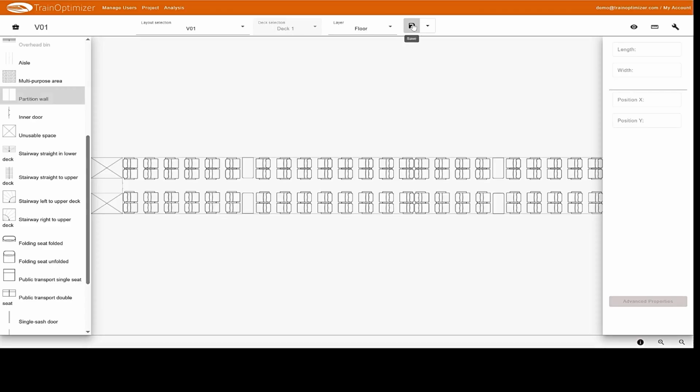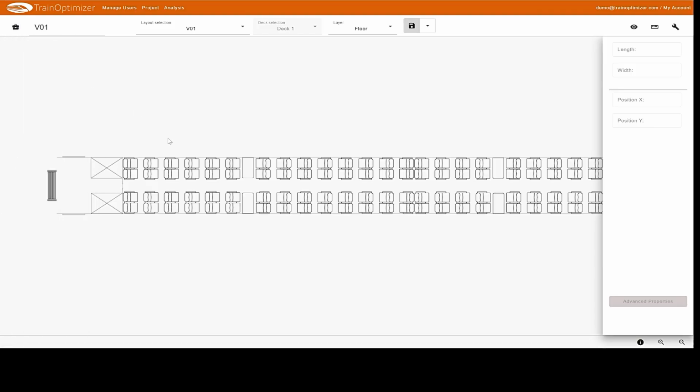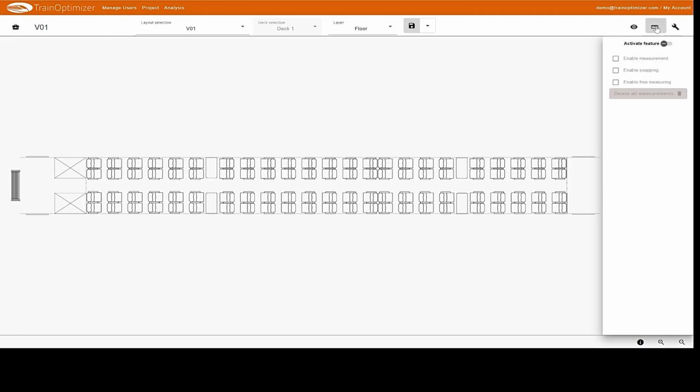Now we want to insert a corridor. To dimension it correctly from the outset, we use the measuring tool again. Measure the distance from one door to the other and determine that the corridor is 21 meters long. Here, too, we do not need to specify the measurement down to the millimeter. However, if you are planning for regional or urban transport, it makes sense to draw the aisles as accurately as possible, as the standing room capacity is also calculated using the element aisles.